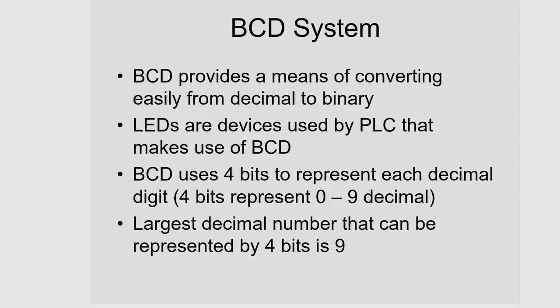So what does it do for us? What is the purpose of BCD? Well, here's a list of a couple bullet points, but there's others. BCD provides a means of converting easily from decimal to binary. So I can go from decimal to binary. You mainly want to do that when you're dealing with 7-segment displays, or something called a thumb wheel.